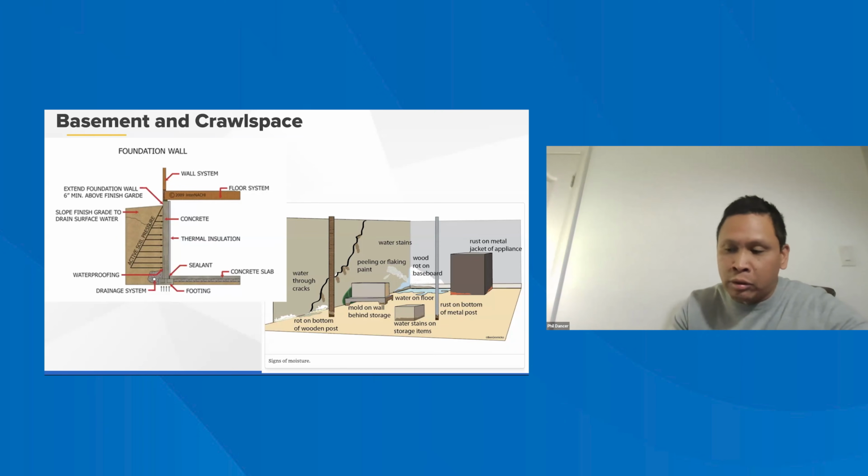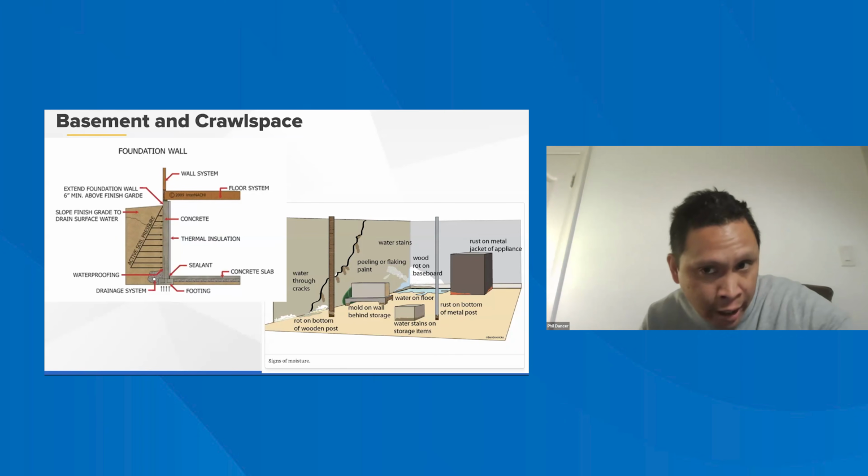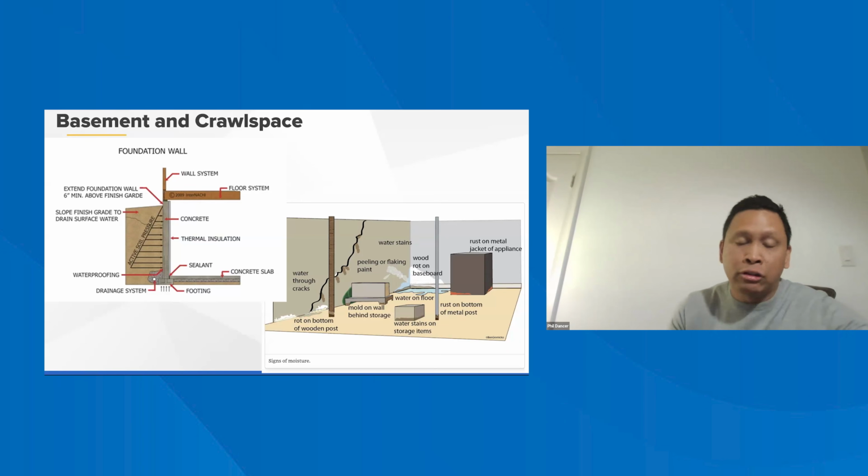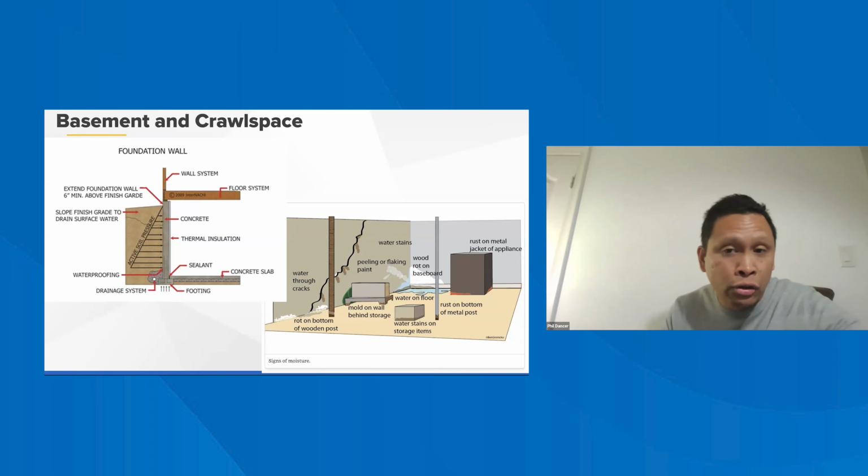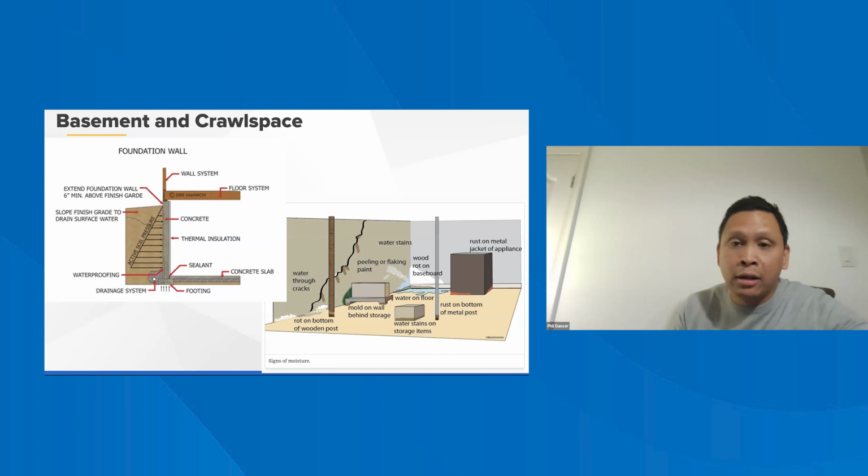There are some builders that will actually say, because we are a high-end builder, our tolerance is not a quarter of an inch, it is actually an eighth of an inch. So if you see any cracking that is exceeding an eighth of an inch, that is exceeding our performance guideline, and we will seal that crack to better ensure that water is not transitioning into the home.